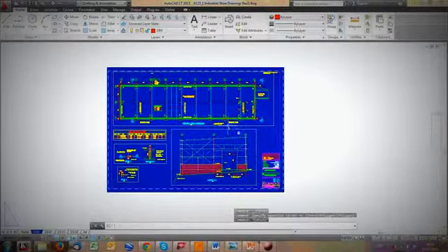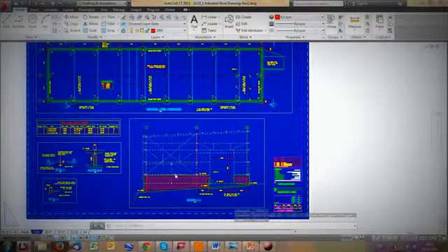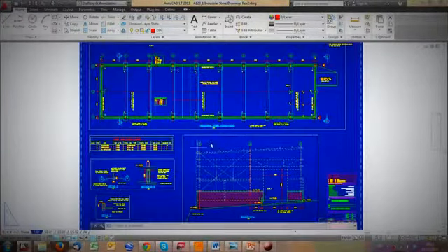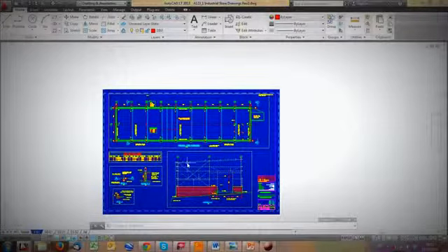But before we finish that, let's just finish up with looking at viewports. So viewports are windows into your model space. And normally with a drawing, you want to set it up at the beginning such that your viewports are there. You know what you're going to put on the drawing, so you know what scale they have to be.